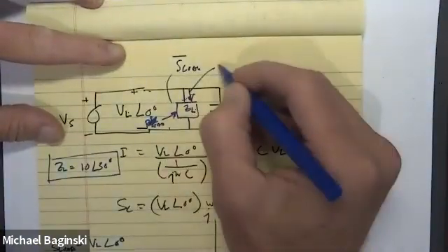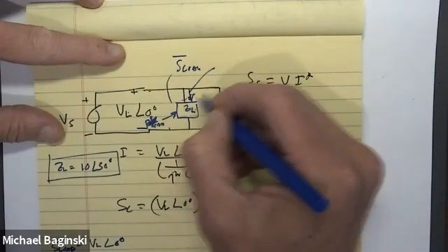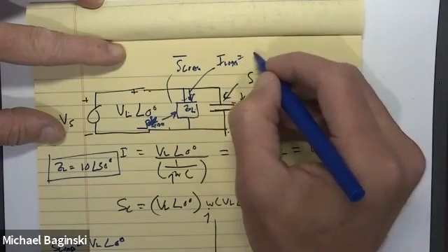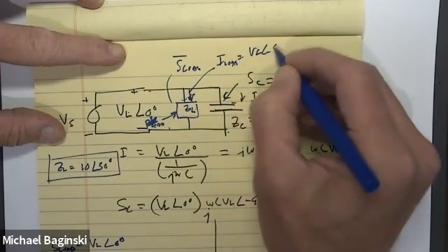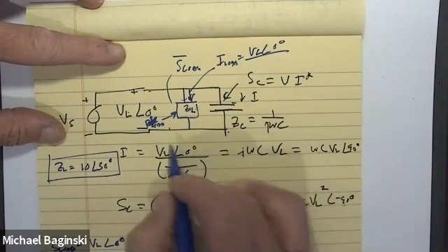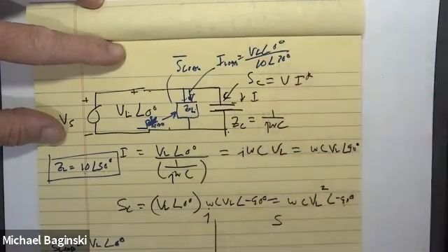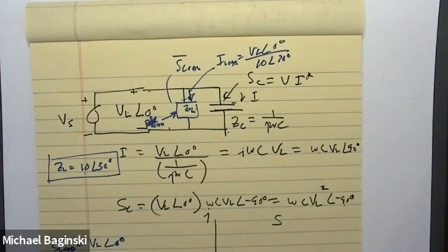It would be this voltage. In other words, this I right here, that'd be I load, equal to VL at an angle of 0 degrees divided by 10 at 30 degrees, right? Y'all follow me? That's the definition of that current going through the load: voltage divided by the impedance. I created an impedance out of thin air, just for this example.